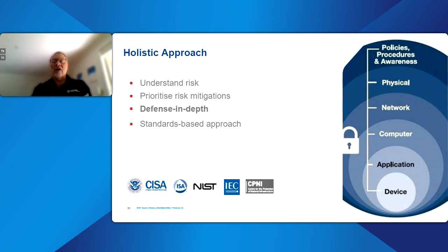On the right-hand side, we've got the defense in depth model. Just because you're using CIP security doesn't mean you ignore defense in depth. Defense in depth means you build layers of an onion to protect your systems. You have a controller, you may have CIP security turned on, but you still lock out any ports in a switch in that cabinet with the controller. You lock the door of the cabinet, you lock the switch room up with an ID card system.